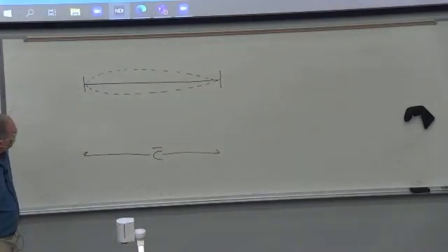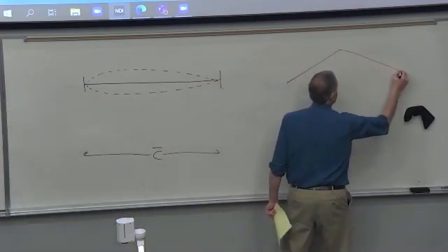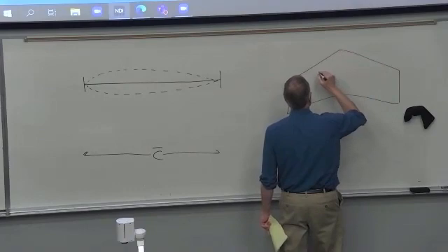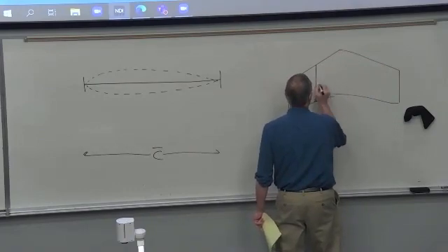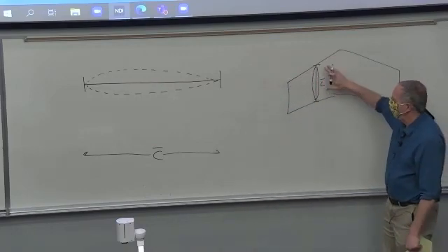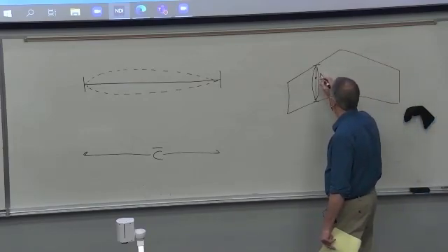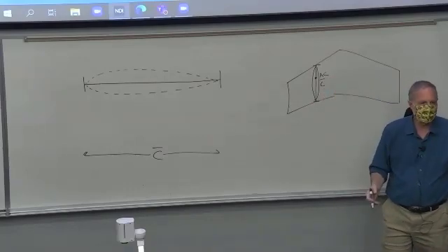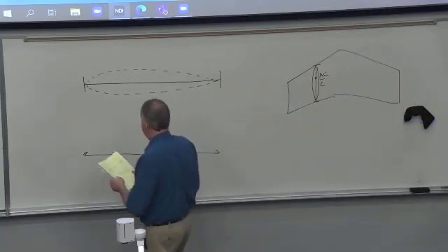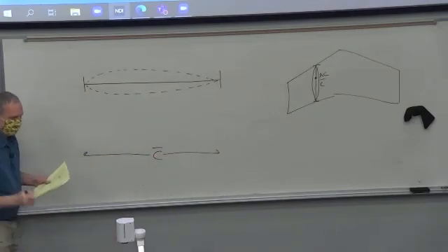But remember that the wing itself, especially if it's one of these tapered wings that's not rectangular, they'll have different airfoils all throughout there. And what we're doing is we're just saying we're going to pick this one part that's the mean chord, and that's what we're going to use to represent our airplane. And we have an aerodynamic center on there where the total net lift of the entire wing acts. That's the resultant of the distributed load over the wingspan. So, but step one, draw C bar and then dimension it like that. So that's step one. Everybody got that?